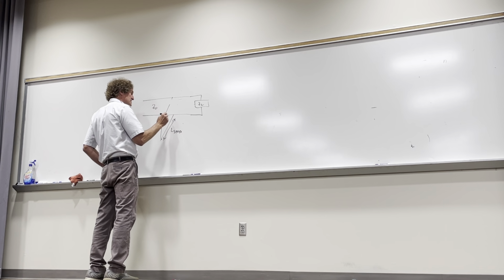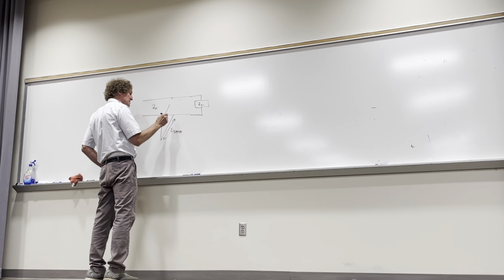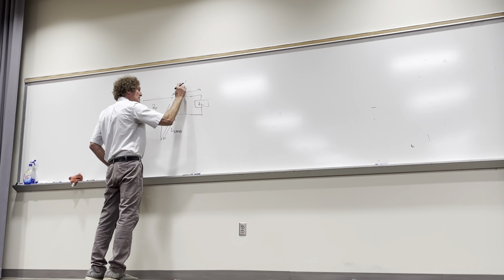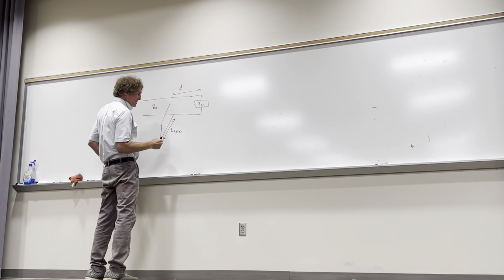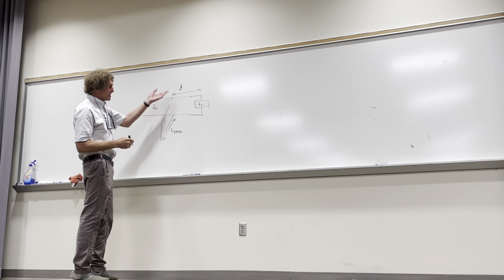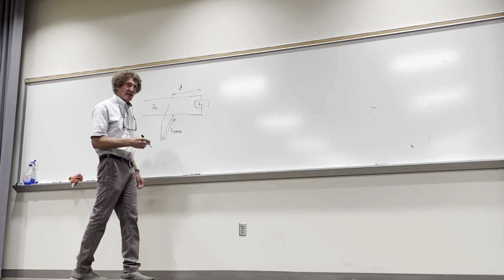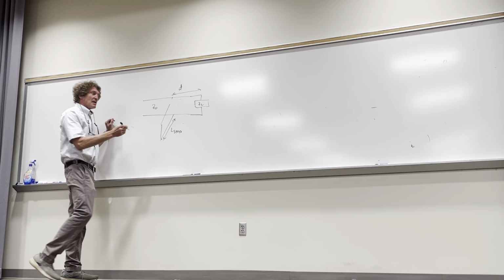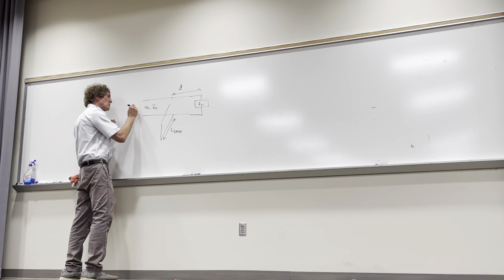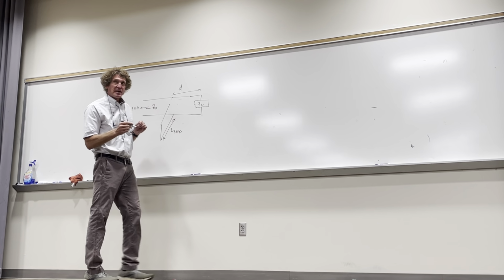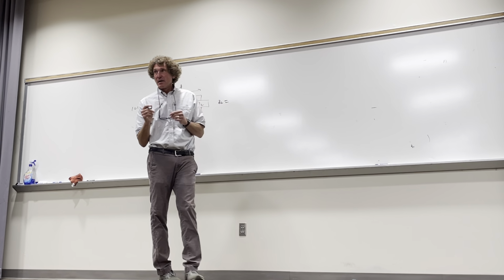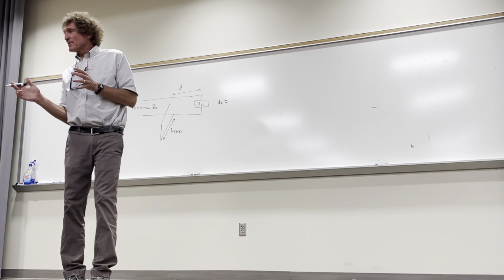The characteristic impedance of stub and of transmission line will be the same, and we have to figure out the distance. We're going to call it D right here. This will be the length of the stub, just the distance from the load. And now we can come up with some loads. If you got values you want, I'll be happy to put it down. For Z naught, I'm going to put 100 ohms. And for ZL here, I'm good with anything. Do you have any?